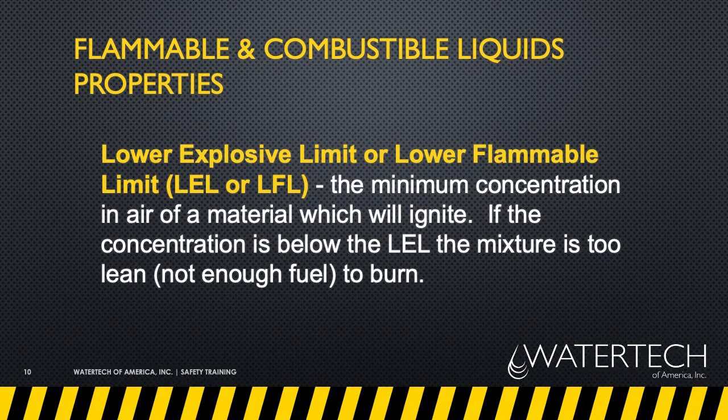For each flammable substance there is a level of concentration in air, usually expressed as a % by volume. The lower explosive limit is the minimum concentration at which a material will ignite. Below the LEL the mixture is too lean and will not support combustion. LEL stands for lower explosive limit.